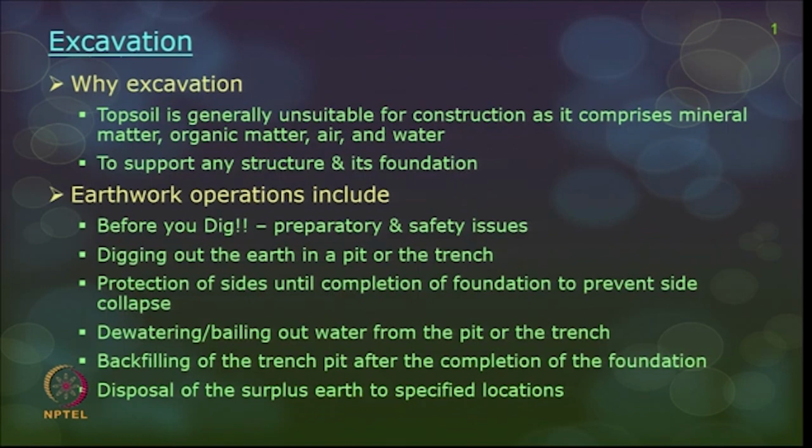Then whenever you encounter a water table, dewatering or bailing out the water from the pit or the trench. Then backfilling of the trench or pit once the excavation or foundation is completed, and then you dump the surplus earth into some specified or marked location. So these are all the different steps you have in earthwork operations, and now we are going to see the different hazards in all these steps. Now let us start with, before you dig, what are the major precautions you have to take.